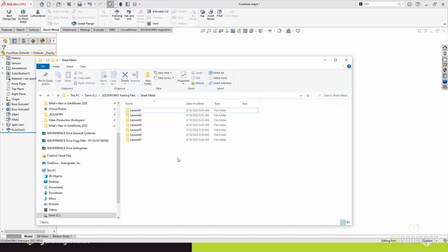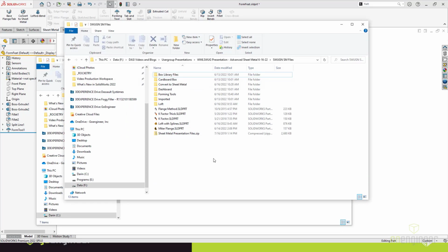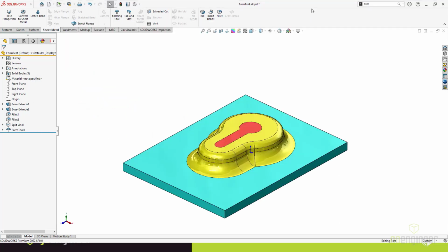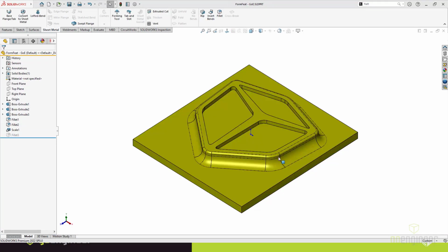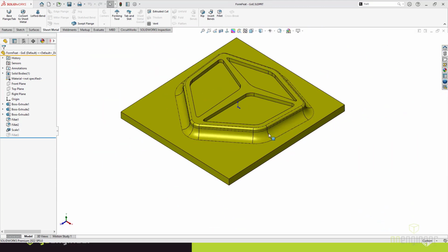That's really the process that it takes to go ahead and make any one of those your own. I'm going to try and find my own one here. There we go. So same kind of thing I was talking about. And again, build it any way that you want to. But the main thing is the radii that are sitting in here have to work for the thickness of the material that you actually put in there.